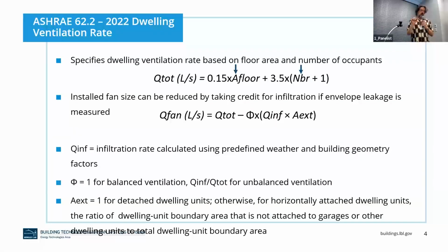So I'll start out with the one I know best, which is ASHRAE 62.2 that I was chair of for many years. And it's basically a standard that says how much airflow do I have to move in order to minimally meet some sort of indoor air quality that would be acceptable. And acceptable, broadly speaking, includes controlling for odors, controlling for moisture, controlling for health. Although we don't separate those things out necessarily in the standard, we just say, here's an airflow.